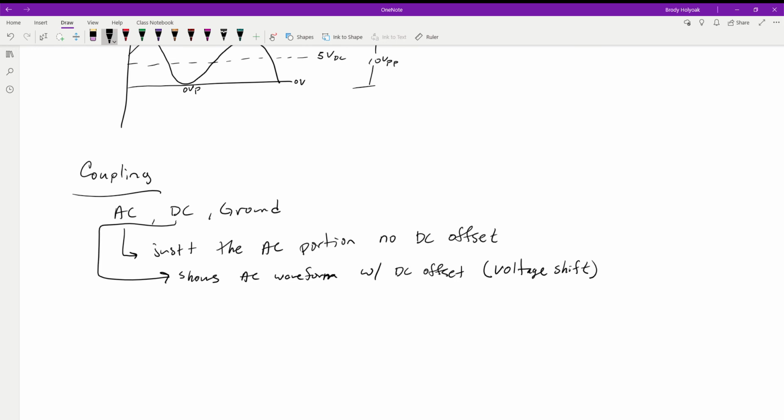So then you want to just look at just the AC portion to see, okay, what is this doing so I can get my min and my max voltages? Because that's how power supplies are rated. It's the voltage ratings they can get to, but it's also the amount of ripple that they have. So a higher power or a higher cost power supply is going to have less ripple than anything else.